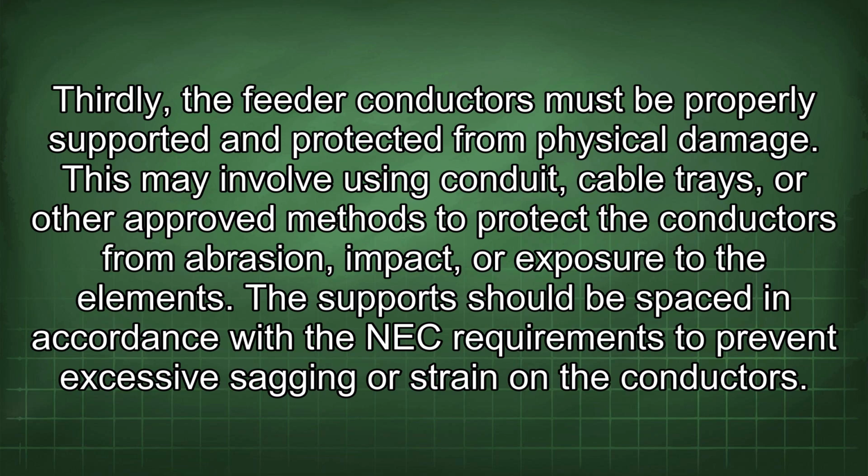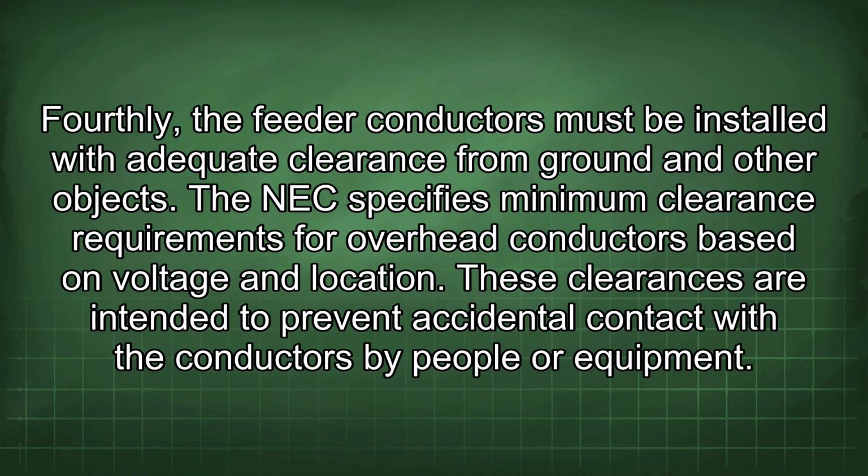on the conductors. Fourthly, the feeder conductors must be installed with adequate clearance from ground and other objects. The NEC specifies minimum clearance requirements for overhead conductors based on voltage and location. These clearances are intended to prevent accidental contact with the conductors by people or equipment.